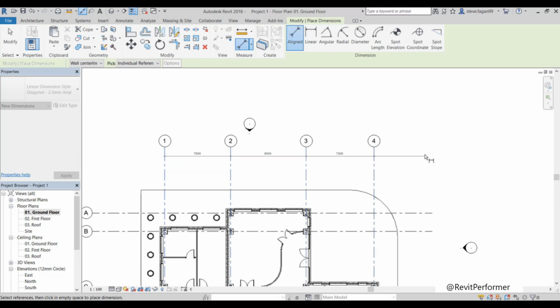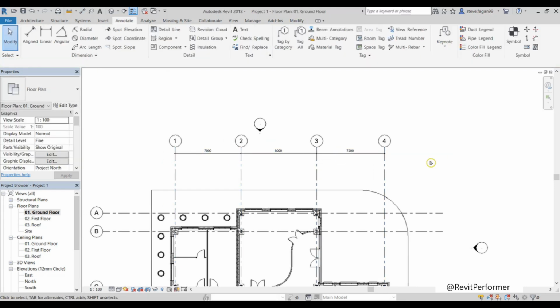The next step is then to position the dimensions where you'd like them to be located. And then finally, to place them, you'll click away from everything on the screen. So if I was to add here, I'd add another dimension, same here. Just move the cursor away from anything else that's not selected and click. If I press Enter, Escape, or Spacebar, it'll just undo everything I've done.